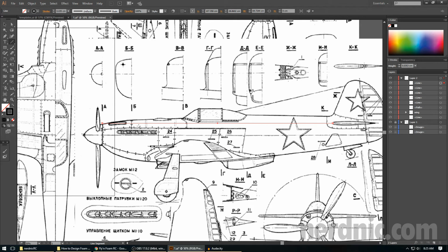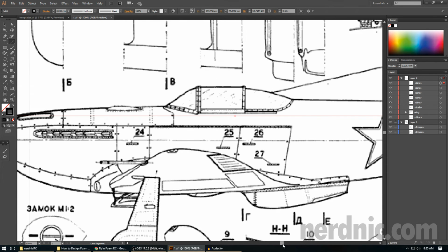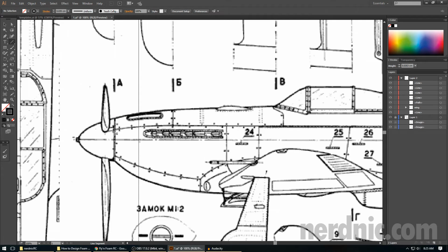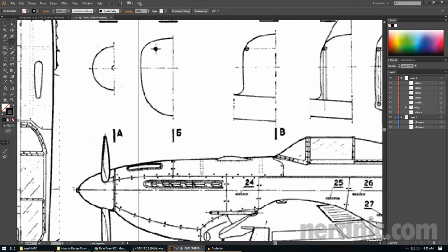Because as you know, we're working with flat foam, and this is going to be folded up, and you're going to have formers on top. So this kind of causes a problem. So how do we deal with this? Well, one of the things that you need to decide is how much curve do you actually want, and then these formers are there to help you understand how much you really need for it to get kind of a scale look. Because what you don't want is you don't want the sidewall of the airplane to come up, and then you don't want like a sharp curve where you can see that joint. You don't want to see the joint between the fuselage foam sidewall and then where the poster board or whatever kind of meets that curve. You want that to be a smooth transition.